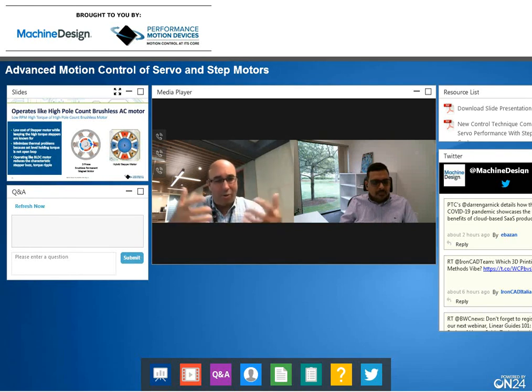Well, there's a large order of magnitude difference of low speed torque control between these two. And really being able to take a stepper motor, which is mass produced and very cost effective, and turn it into the performance that you get of a brushless permanent magnet motor and the smoothness associated with that. Because there's pitfalls with stepper motors when it comes to how you deal with holding torque with traditional drives, the torque ripple and the buzz that Prab was talking about. Those are all things which have caused problems. When you can marry those two worlds together, you get this very cool, cost-effective solution that can do high torque at lower RPM ranges.